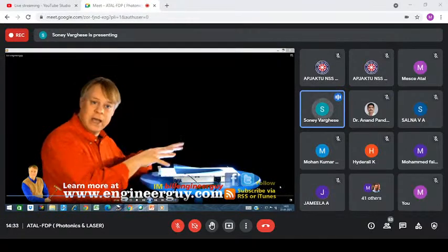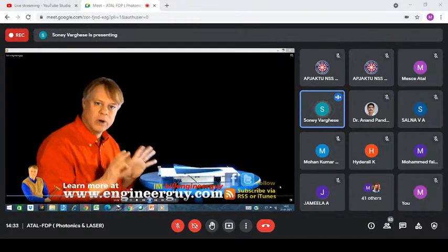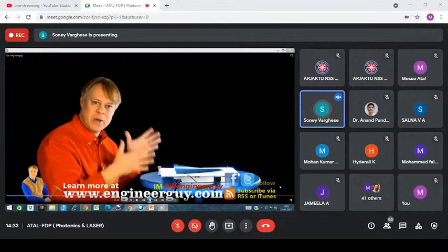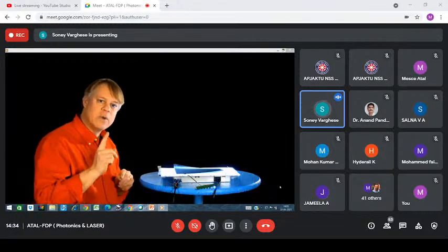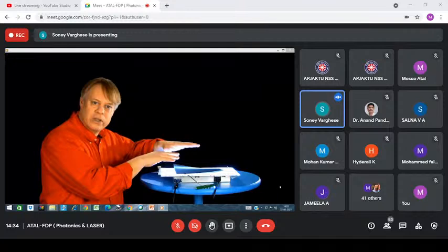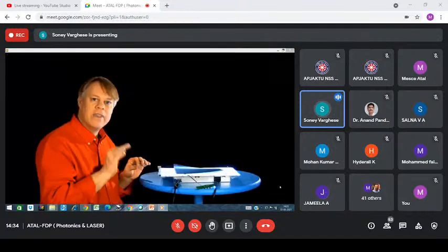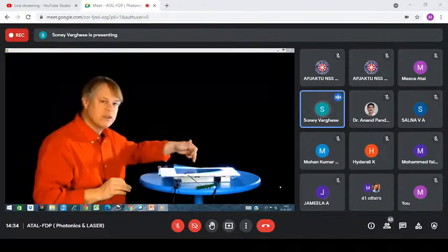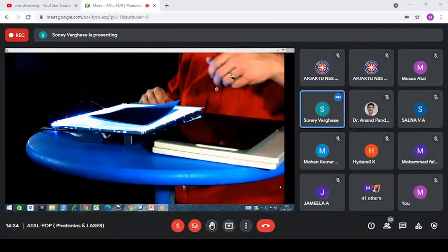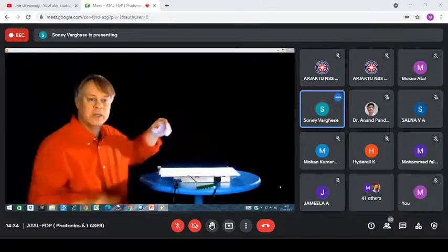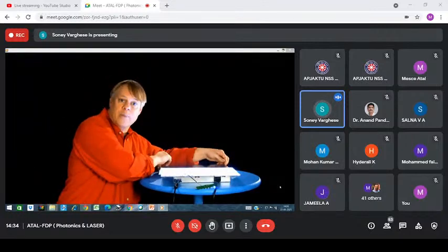Now, of course, in this LCD monitor, the front polarizer doesn't rotate. Other than the on-off switch, the monitor has no moving parts. Instead, we place these 2 polarizers 90 degrees to each other, a configuration that allows no light through. And then, if we want light to pass, we twist the light within the glass pane to match the front polarizer. How? Well, it's a simple-looking piece of glass that does all the magic.